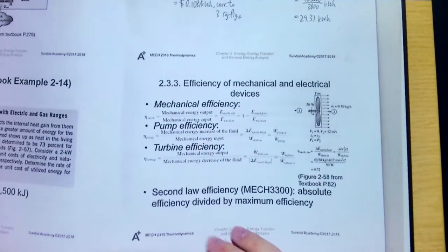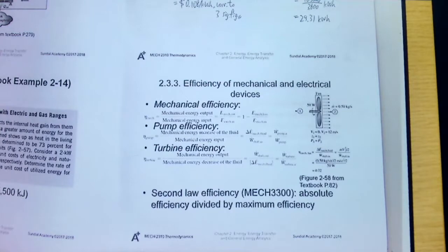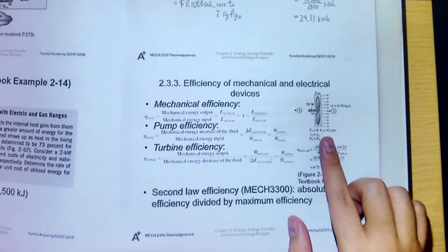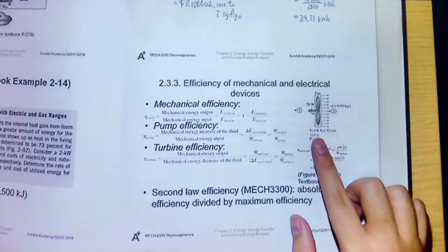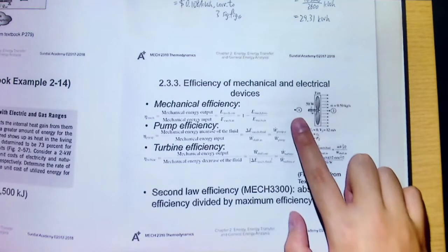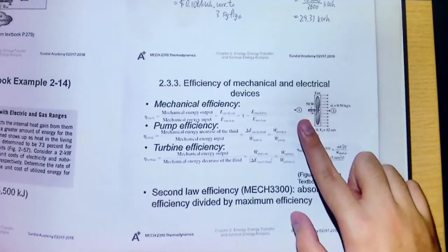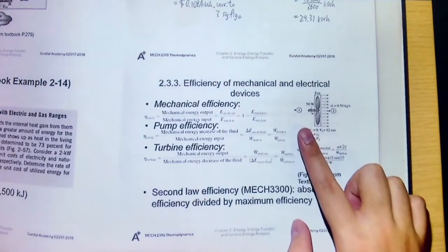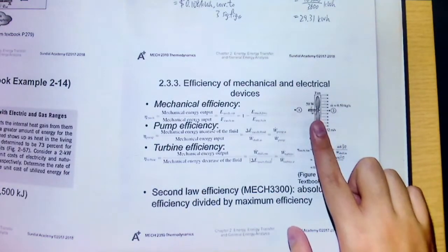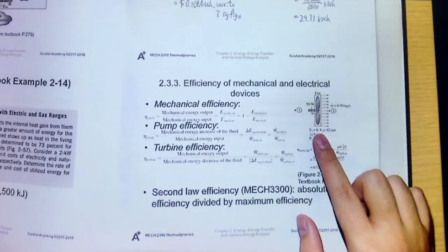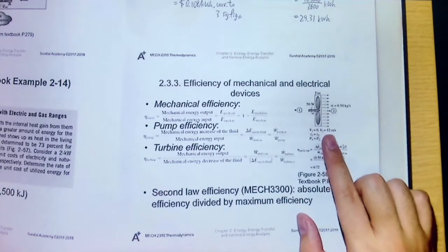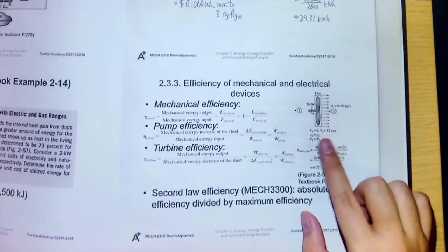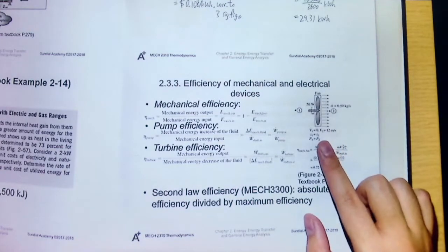Okay? Here is a little example on how to calculate the mechanical efficiency of a fan. Suppose V1 is 0 and V2 is 12 meters per second. That means originally at this position there would be no kinetic energy. But of course, there should be some kinetic energy so that it can get into this fan, but we set it to 0 so that we can get the KE. And V2 is 12 meters per second. The elevations are the same and the pressures are the same, so that we can find out the efficiency